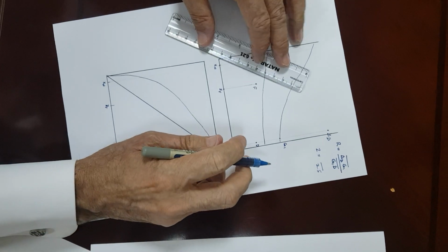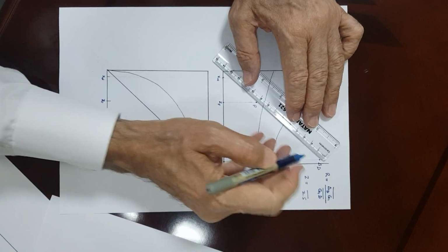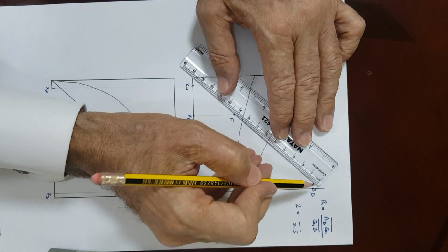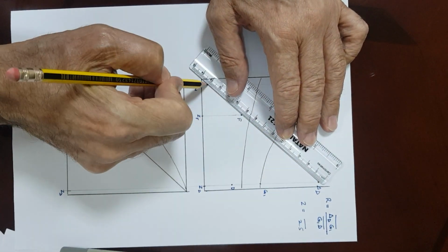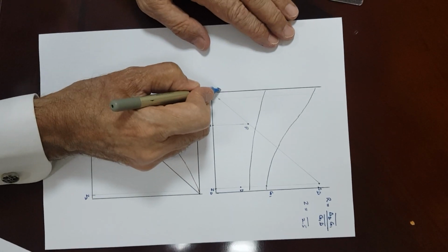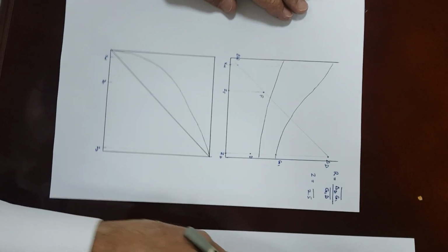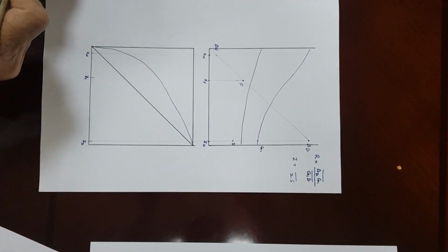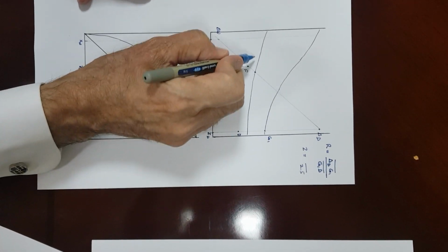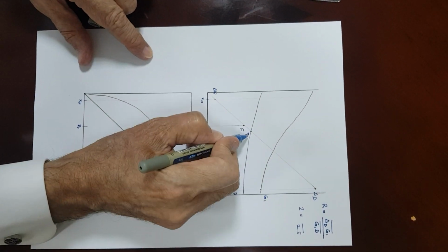The next step is to find the position of delta W. Delta D, F, and delta W fall on a straight line, so you just draw a straight line between them. The intersection here will give you your delta W. So we finished with the first step. Another important point is the intersection with the liquid enthalpy line here. Let's call that point T. It's a transition point.